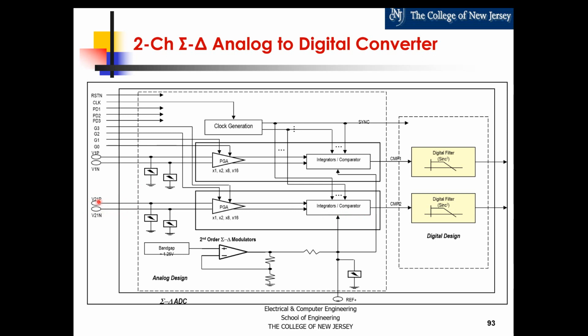So here you have differential analog signaling coming in, and now here you get a digital output. It's a high speed 1-bit digital output. Okay? In other words, this modulator implements what is called a 1-bit analog to digital converter, but it's high speed.